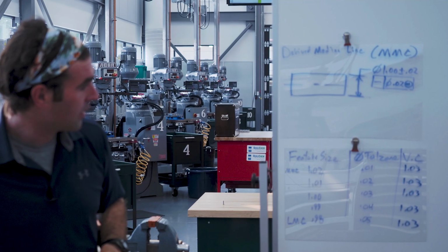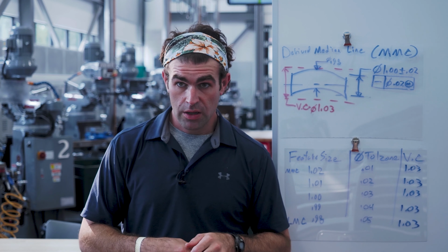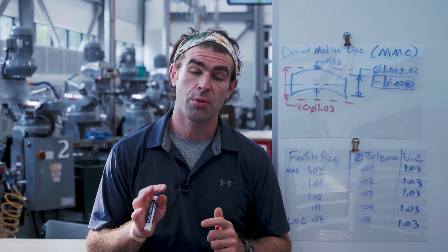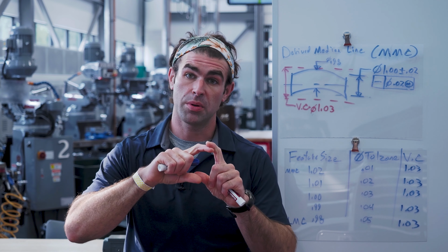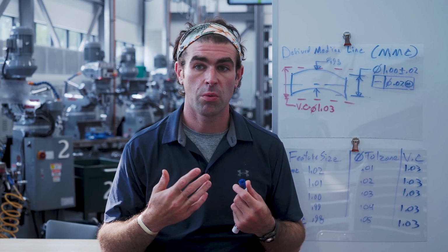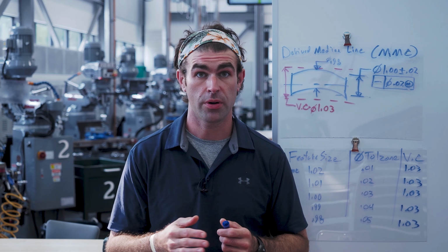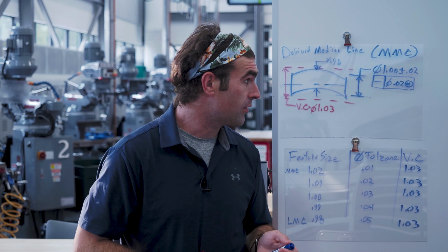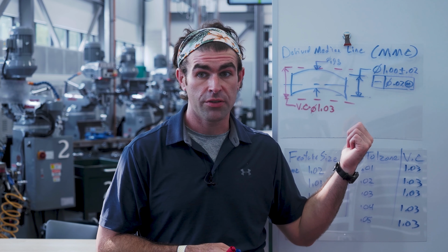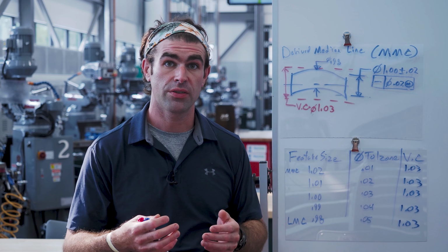So it kind of looks like, if that part came in with a diameter of 980 thou, right? We have the maximum tolerance on the derived median line of that. So it means that it can be more bent, but it still has to come in this virtual condition, this 1.030. So we can check the size with calipers or whatever and make sure it meets at least the size restrictions. And then we can use a hard gauge. We can have something set to 1.03 to make sure the part is good.